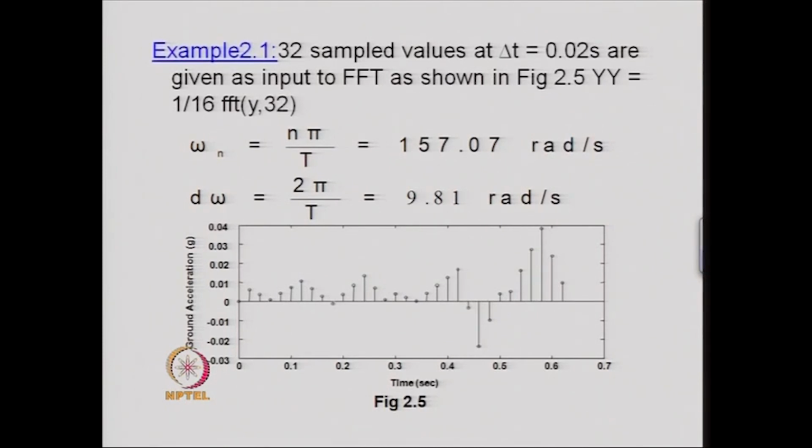For making a simplified calculation, we considered 32 sample values at delta t equal to 0.02 second, and the FFT of that is carried out.